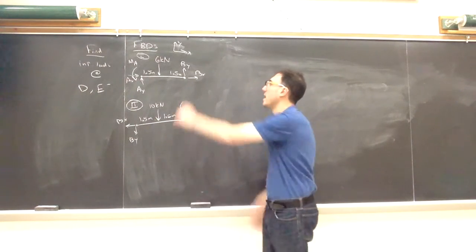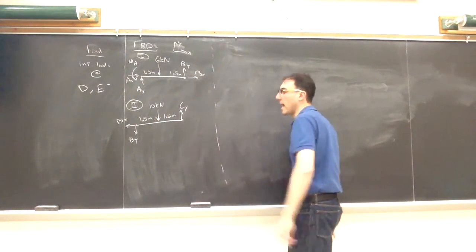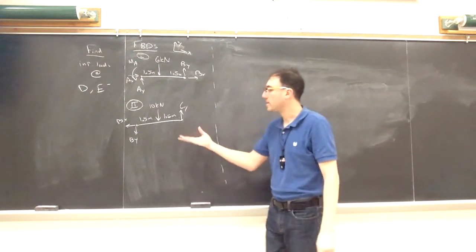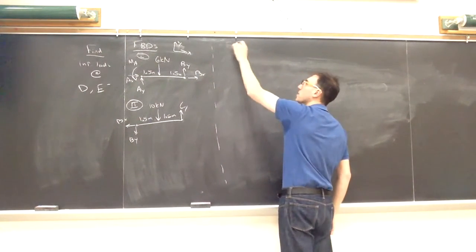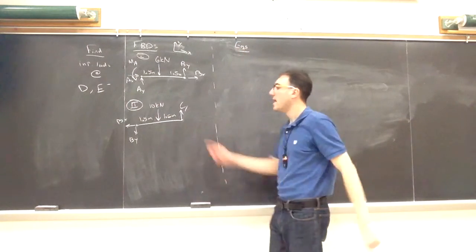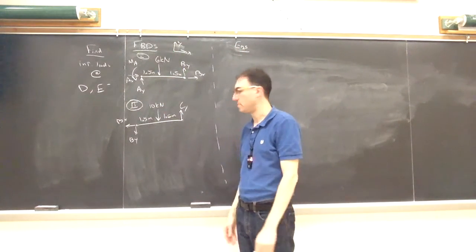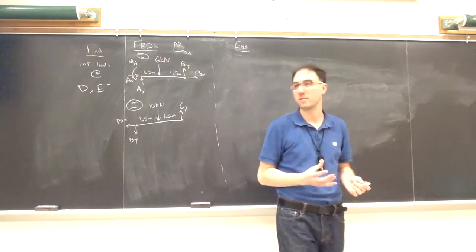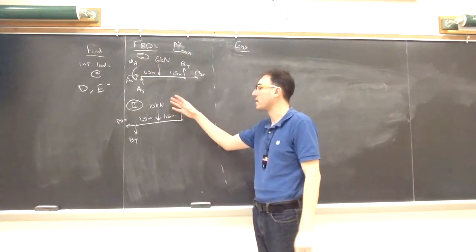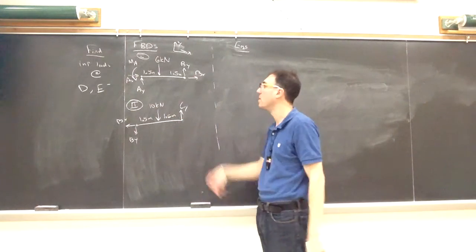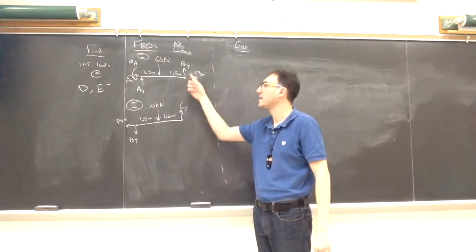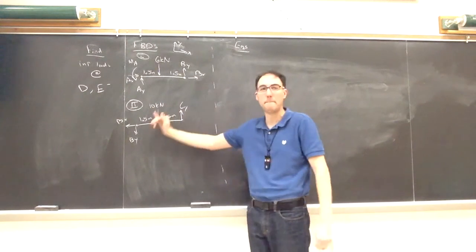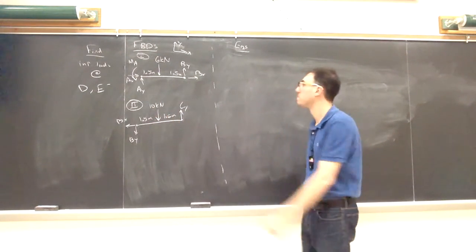And looking at free body diagram 2, I only have 3 unknowns in this picture. So I would say mathematically, it's going to be easier to start my equations with my second picture and then use that information to find the first picture. At this point, I'm still just solving the frames and machines problem. There's no internal cuts, at least through material. It's internal in that this pin connection is internal to my structure, but it's not actually internal to any member in my structure.